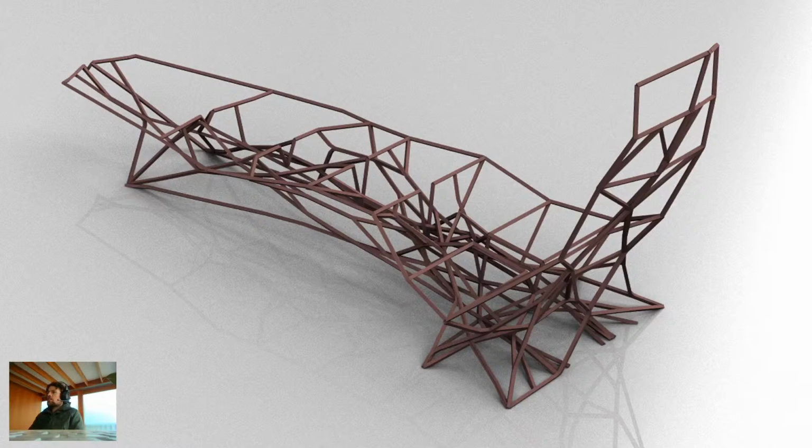So it's a particular scale, it's modeled off of the body, it has some kind of ribs for attaching some sort of surface to the top of the chair, there's places where it touches the ground, there's a sort of formal language that I was interested in where things bundle. And for those reasons, to capture some of those ideas in the 3D model is actually very, very fast. This thing took about 20-30 minutes to model. But ordinarily, you would then spend hours and hours rationalizing it so that it could be built. And if it was going to be built by a fabricator that typically works in 2D, you might spend days rationalizing it into 2D parts, and the design would inevitably change quite significantly.